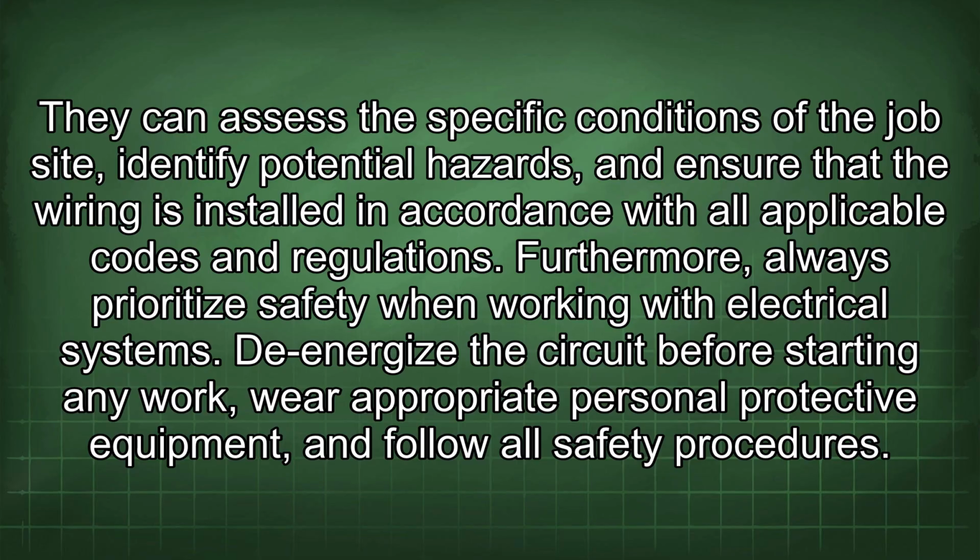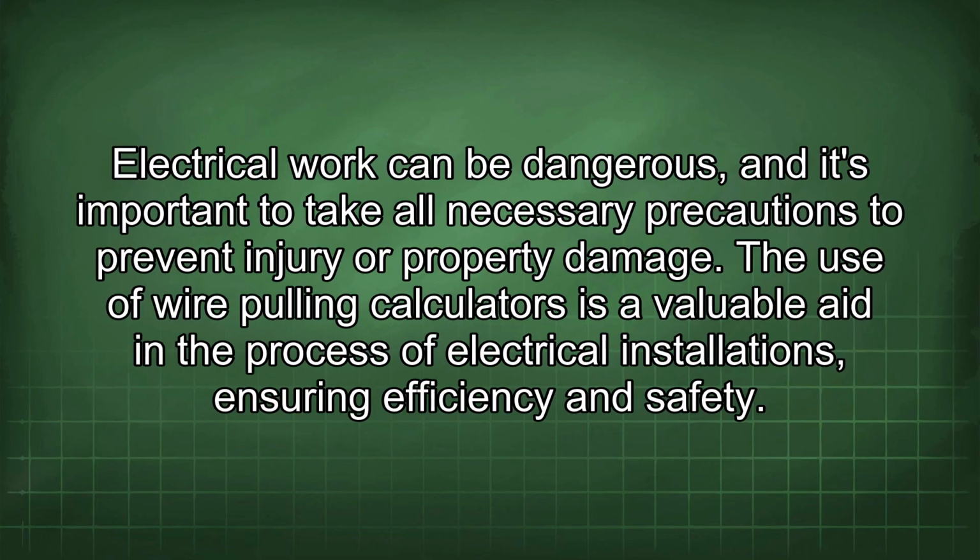Furthermore, always prioritize safety when working with electrical systems. De-energize the circuit before starting any work, wear appropriate personal protective equipment, and follow all safety procedures. Electrical work can be dangerous, and it's important to take all necessary precautions to prevent injury or property damage.